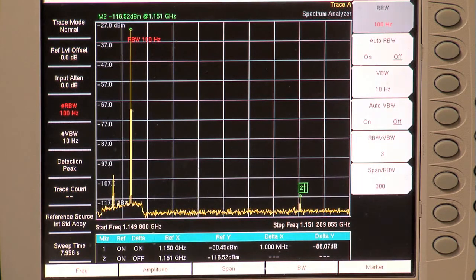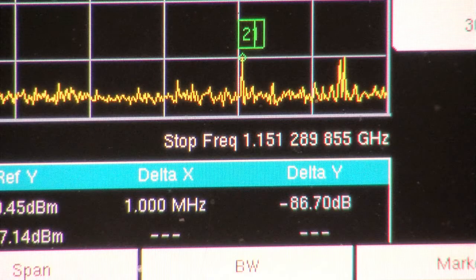Direct measurement is an excellent way to determine dynamic range. Start by measuring a very small signal by itself. This is easy to do with a marker. Then turn on a large signal and place a delta marker on the large signal. Use the marker table to see both values at once. While observing the measured amplitude of the small signal, change the large signal amplitude until the measured value of the small signal is reduced by 1 dB. The delta marker gives you the dynamic range value.